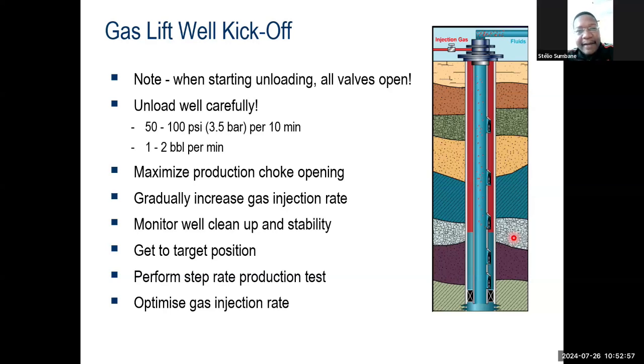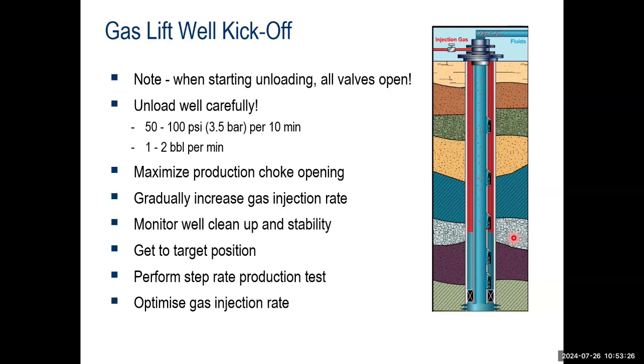Yes. Okay. All right. So regarding the material of the gas tank, it needs to be suitable to the production fluid. So if your production fluid has a lot of CO2 or H2S, then you need to consider metallurgies in stainless steel or better. But if there is a lot of water and very little oil, then you can actually settle with carbon steel.